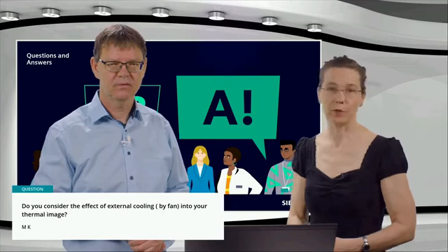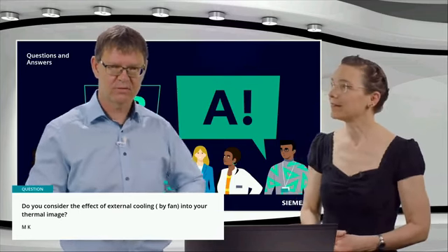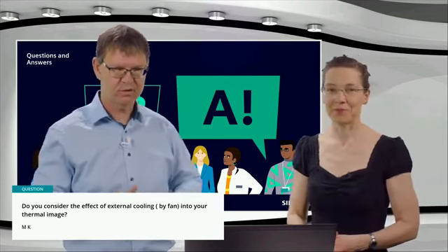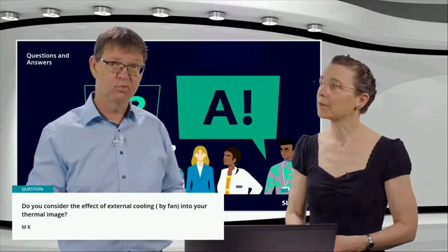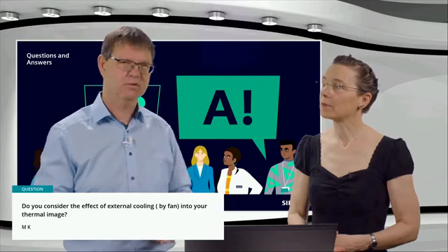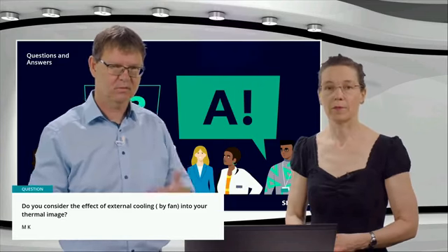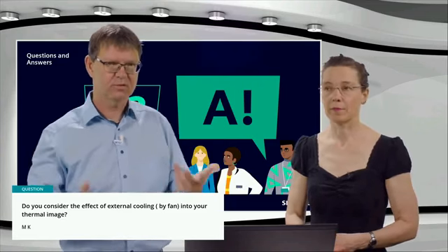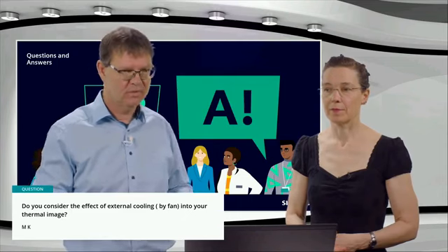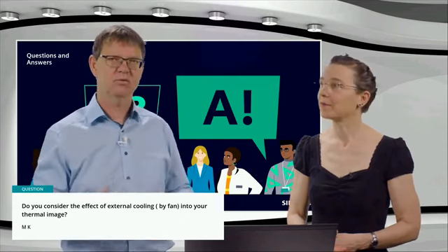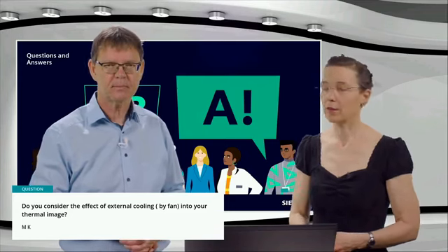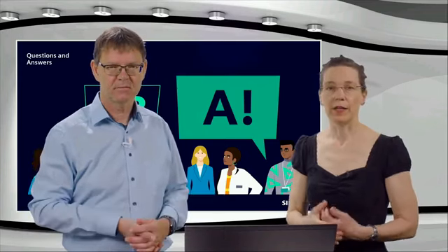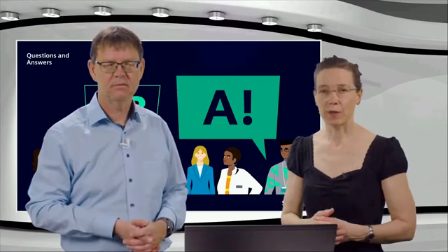Oh, perfect. Thank you. So if you have permanent external cooling which is not connected to the rotor movement, then you can assume the same time constants for starting up and for standstill, because the cooling effect is the same. Or maybe it's a little bit less, then you can also adapt this with the different time constants. Thank you, really helpful.